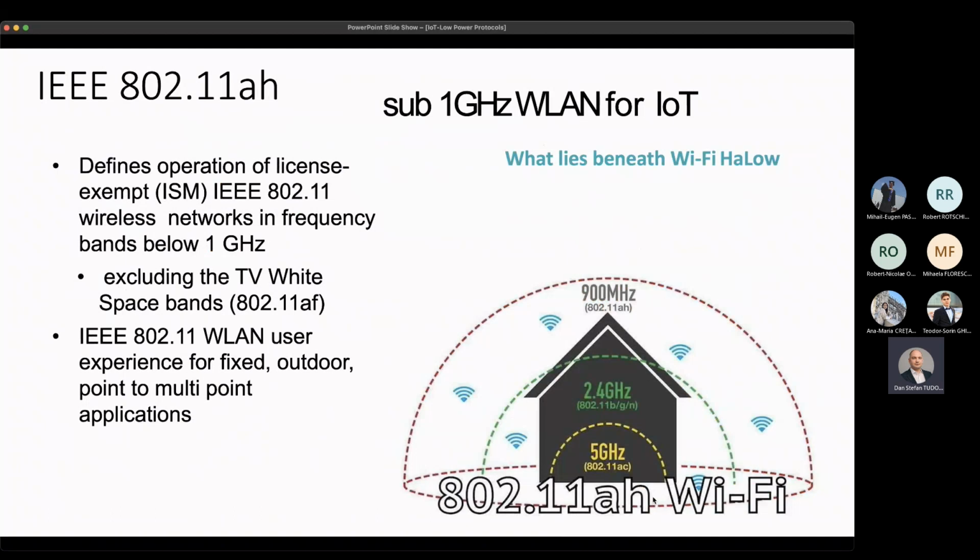Another interesting protocol is the IEEE 802.11ah standard, which is also called Wi-Fi HaLow. It's spelled H-A-L-O-W, but it's called Wi-Fi HaLow. It's a standard which defines communication through 802.11 wireless networks. So it might be compatible with some routers or switches that actually employ this standard. But it uses the sub-gigahertz frequency spectrum to communicate.